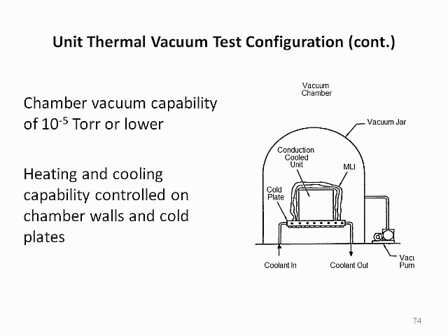Thermal vacuum testing must, of course, be conducted in a vacuum chamber. The chamber should have a vacuum capability of 10 to the minus 5th torr or lower. Heating and cooling capability is provided by the chamber walls, cold plates, ancillary heaters, and lamps.